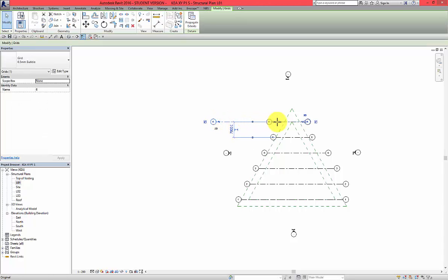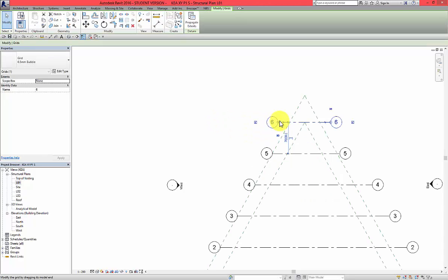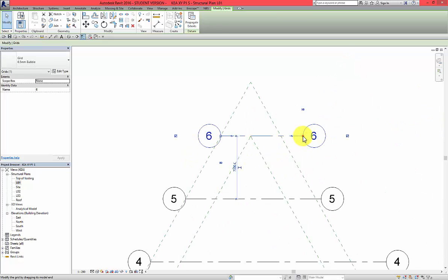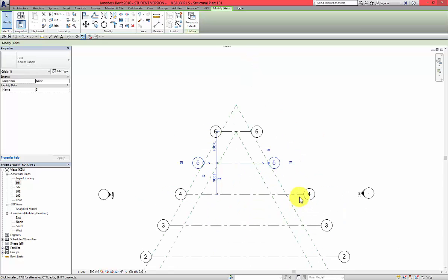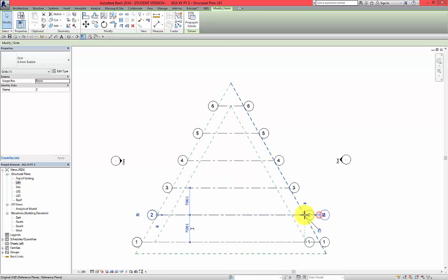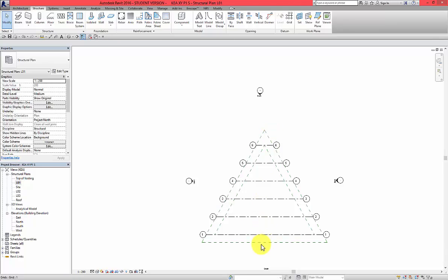So what I'm going to do, I'm going back to this empty circle to get 3D back, and then when I have 3D, I'll snap to the reference plane, select this, and this one we need to unlock it. Okay, that's the first set. We're going to create two other sets on both sides.